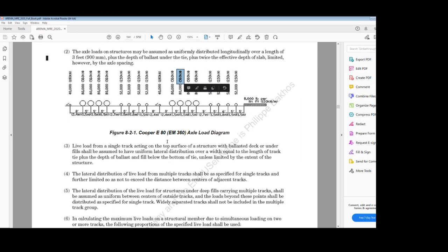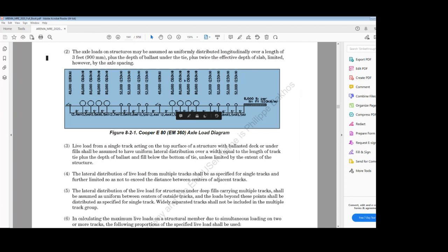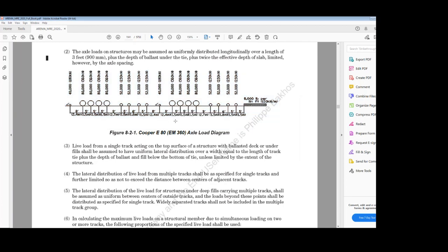Okay, so this is basically a freight train, the one they call goods train, and the speed of a freight train is mostly not more than 160, meaning the top speed of this freight train is around 160 kilometer per hour. And this is the configuration and the spacing, axle load, all this is given here. So basically the maximum axle load is 360 kilonewton and the spacing between these two axle loads is 1.5 meter. Okay, so we apply this live load in our structure in two ways.